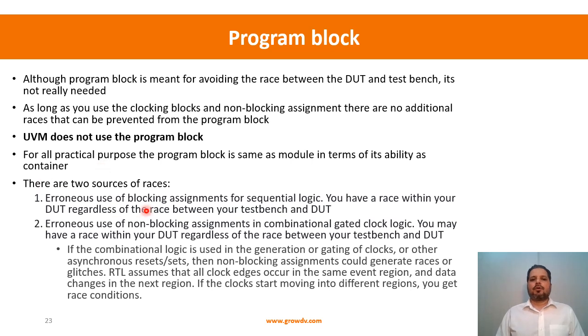Predominantly, at a fundamental level, there are two types of races. One is the erroneous use of blocking assignments for sequential logic. We have seen several of these scenarios with blocking assignments. This is a race that can exist in the DUT regardless of any race between the testbench and DUT. So if you do this, whether you use a program block or not, that particular race is going to exist.